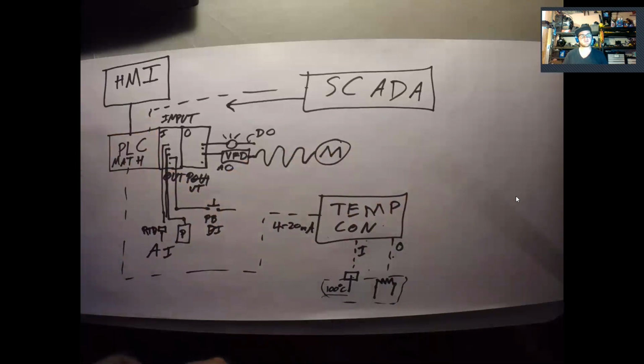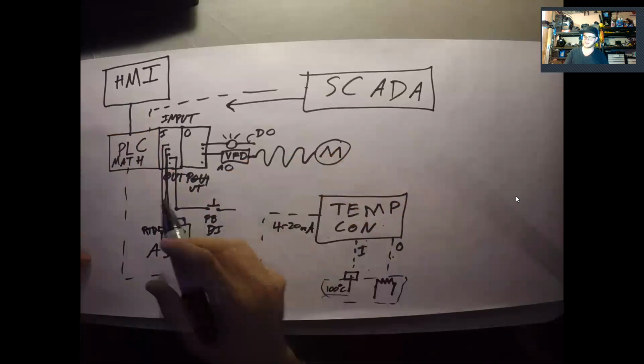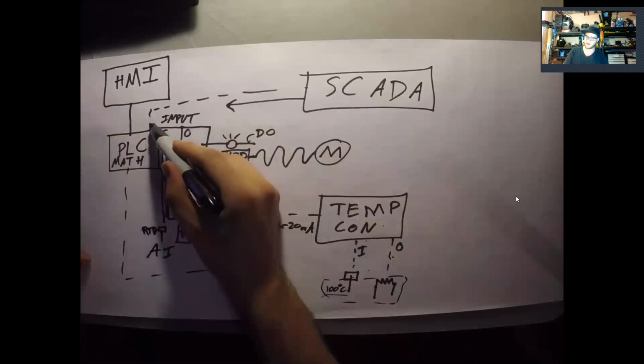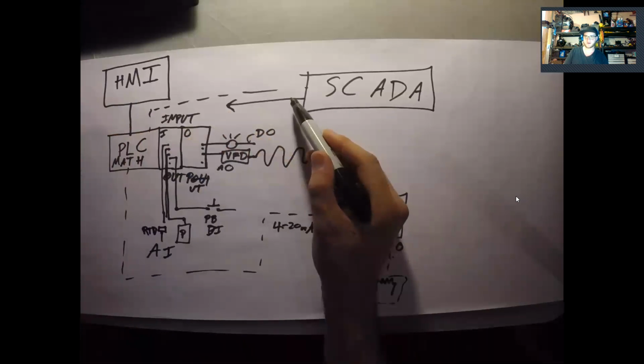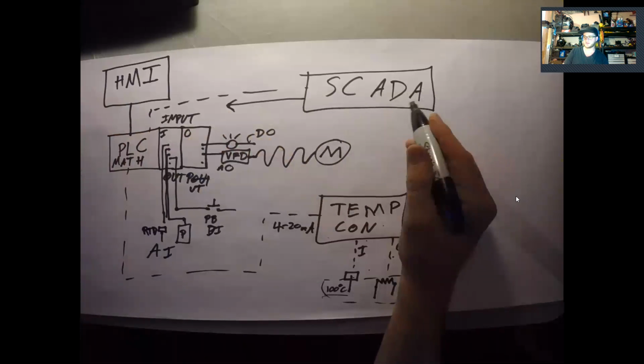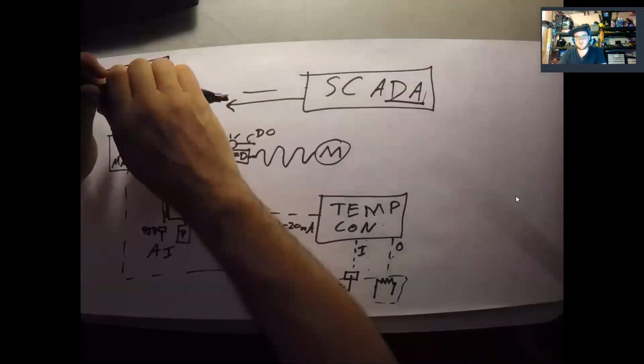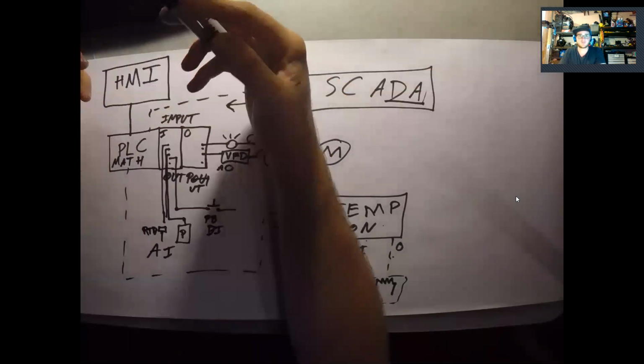And so in pharmaceutical plants and whatnot, all of this gets validated, and a lot of times that reporting of process set points gets recorded into the data historian that's part of the data acquisition of this control system, and it gets put into batch reports, and ultimately that kind of stuff is submitted to the FDA.